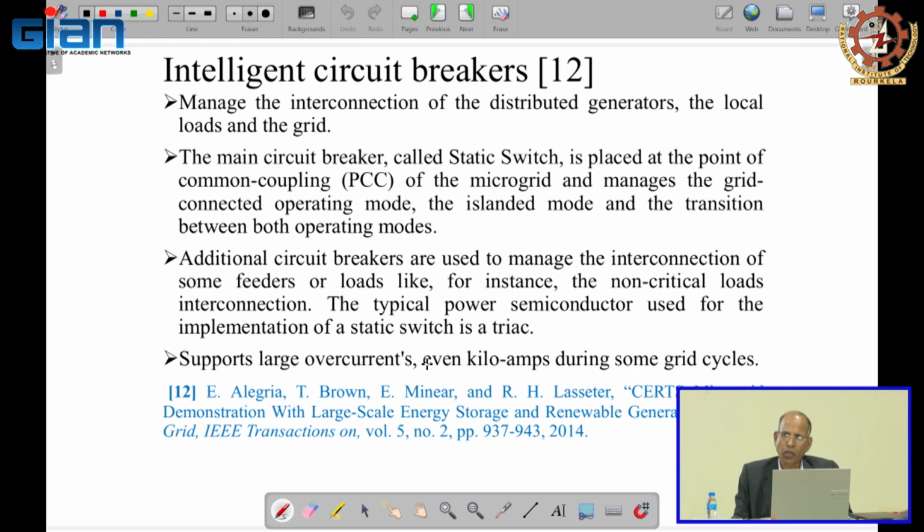Okay, so here we cannot depend upon a human being. The power has gone, and then some person will come and operate the diesel generator. It can take 5 minutes, 10 minutes for the person to operate. Sometimes the person has gone for taking tea, so it can be half an hour. So priority loads cannot wait for that time.